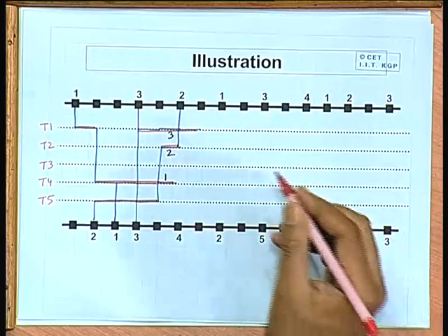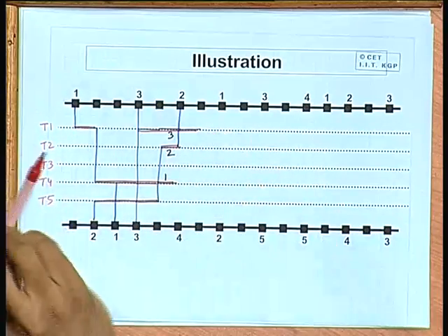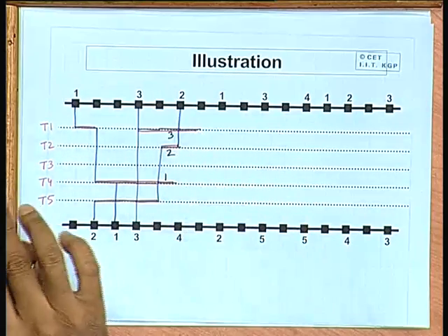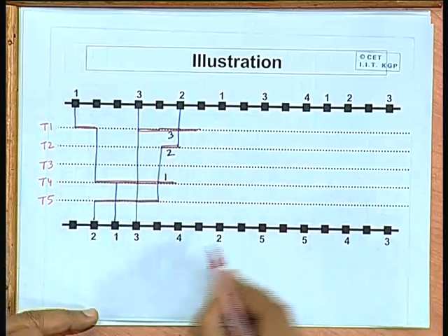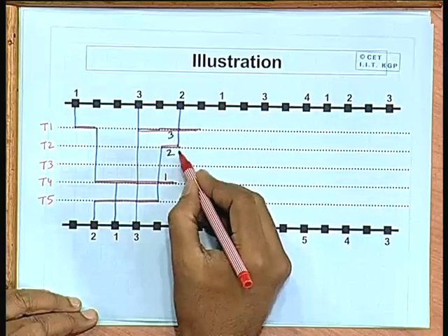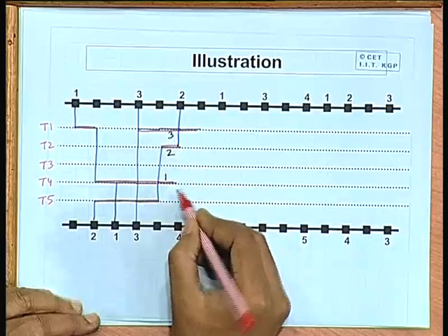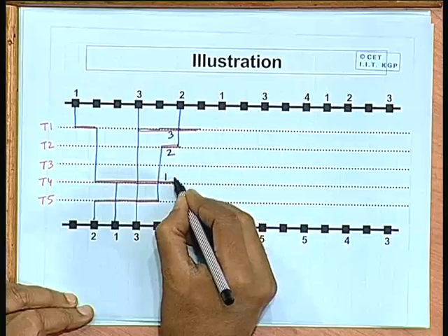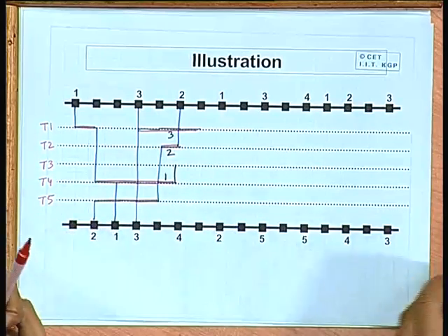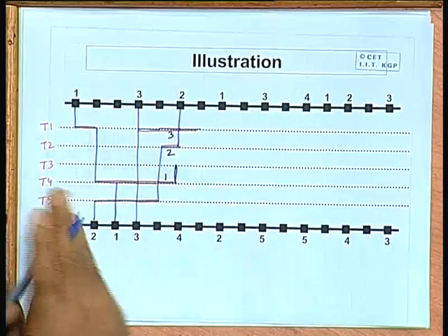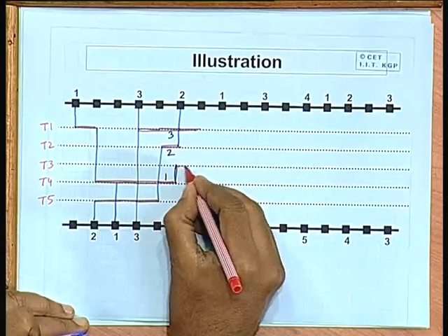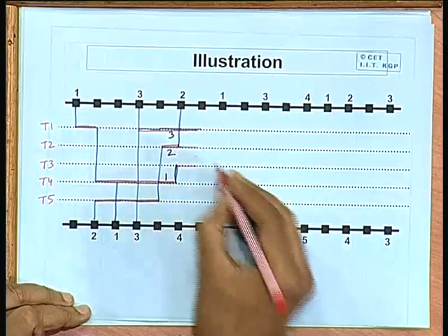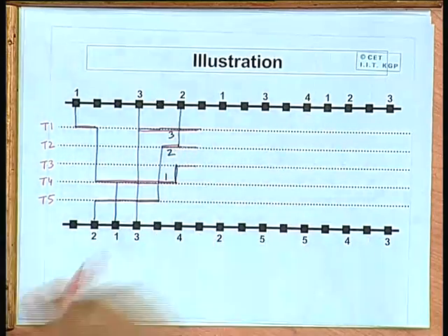Okay. So, now at this column position, this 3 is proceeding like this, and 2 will also proceed because 2 also has a connection down, but it cannot go down here. Well, this 1 will take a jog, 1 has the next terminal here. So, this 1 will get a priority, okay, let us take blue, going up like this. So, 1 will go up and this 2 will also continue because 2 has a terminal like this. So, in this way it will go on.